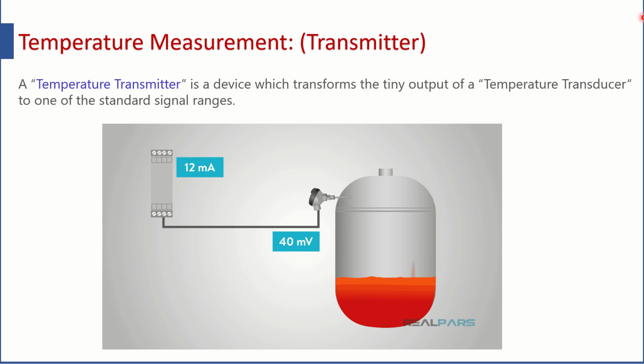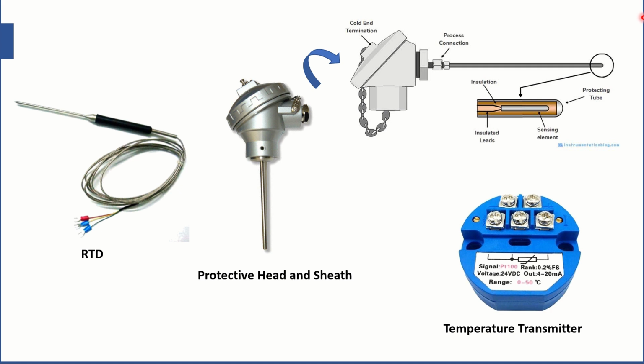So dear participants, welcome back with our discussions on temperature transmitters and temperature sensors. We have seen what is the difference between them in our last lecture. We have seen that sensors can generate signals which are of some non-standard format that cannot be understood by standard industrial equipment like PLC. In order to transform this non-standard signal into a standard and globally accepted signal, we need to use temperature transmitters.